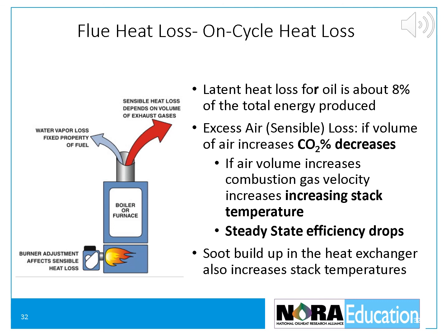Excess air, or sensible heat loss, is also called chimney loss and is the amount of energy that leaves the building along with the combustion gases. The chimney must be heated in order for it to operate. The larger the temperature difference between the combustion gases and the outdoor temperature, the stronger the draft. Therefore, the chimney must be heated to create the draft needed to draw the gases out of the building.